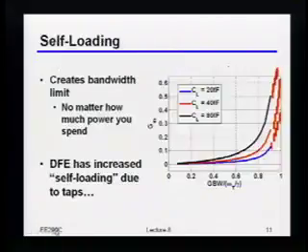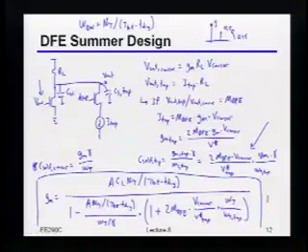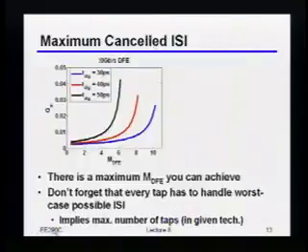Okay, so again, what I really like about this particular formulation is that it tells you very quickly how much power it takes to build a certain type of DFE with a certain amount of correction. And in fact, it's really easy. Once you know what the load cap and the gain bandwidth you need is, you can figure out how much power that would take, just based on this relative factor on the bottom here.